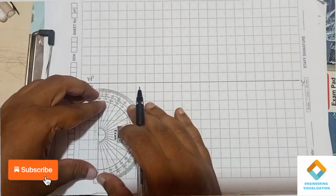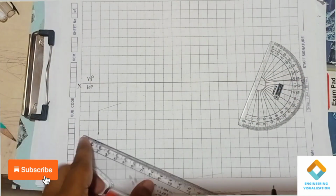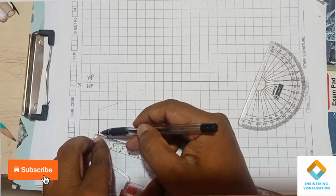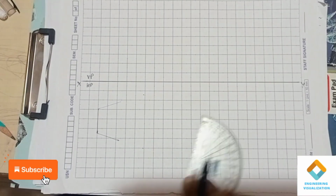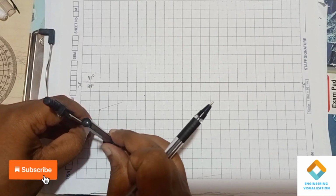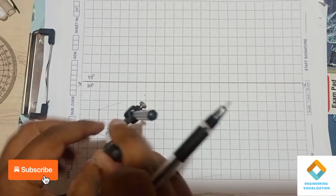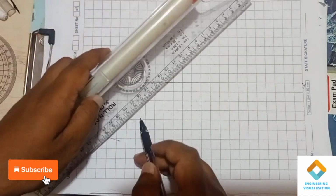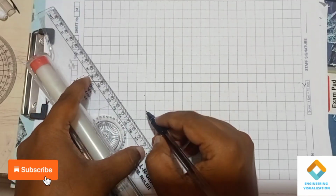Same way on this end also we have to mark an angle of 72 degree, and draw a line passing through that angle point, length 25 mm, that is 2.5 centimeter. Now using the compass, measure 25 mm and cut the arc. Measure any one of the lengths here, because all the lengths are 25 mm only. Keeping at that reference point, cut the first arc, and keeping at the second reference point, cut the second arc. Now you are getting a cut point, so join that arc cut point with the end points using a straight line with the scale.